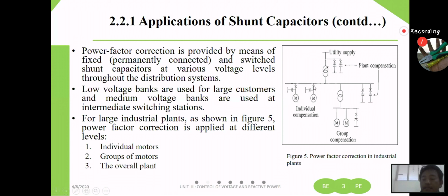As an example, I have given 33 kV here. We have to maintain 33 kV, which is an acceptable limit, right? If it is below 33 kV, then it will not be within an acceptable limit, which means if you prolong using this, your motor will get damaged, or it will not function at full efficiency. Your production may go down.